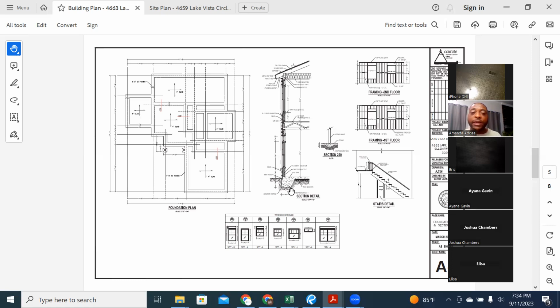And so if anything hits the house, if any electrical thing malfunctions, instead of you getting electrocuted, everything's going to shoot straight to that ground wire. It's going to go right to the ground rod, which is your rebar sticking up, and that's going to get grounded through that rebar, which is encased in the concrete. Okay, so it doesn't harm you. It grounds the wire, and the house is properly grounded.